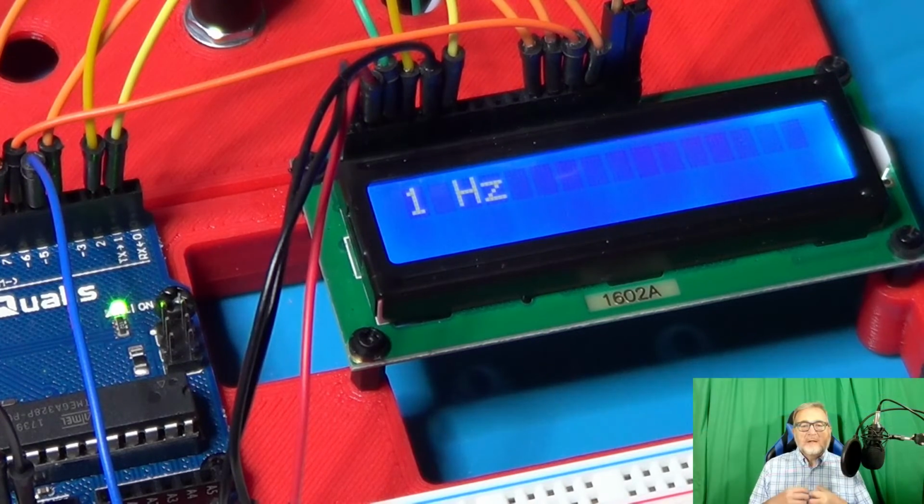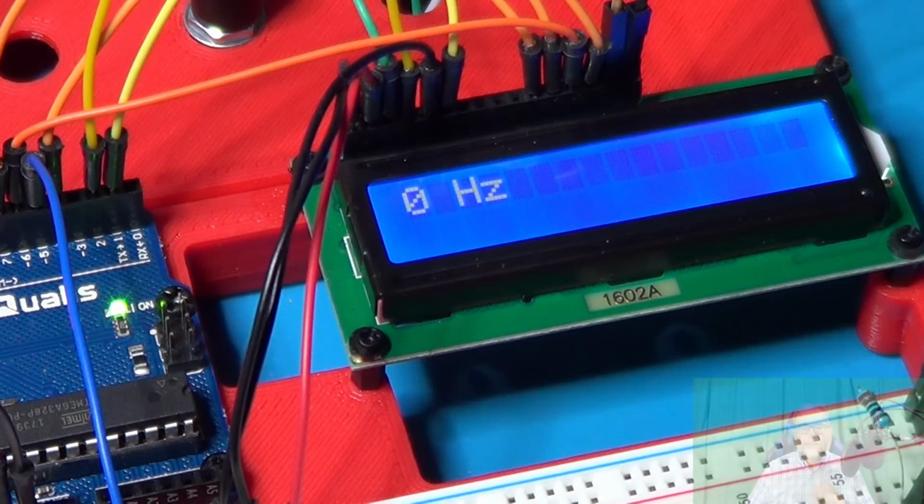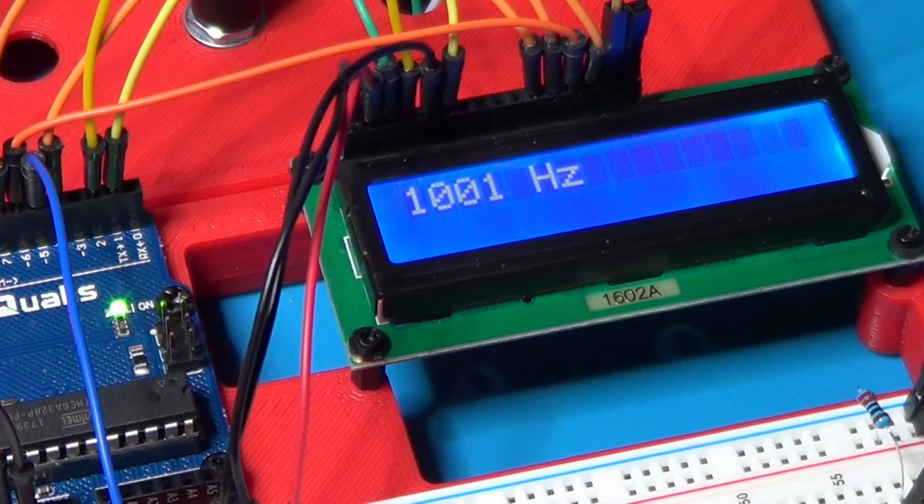So it looks like this frequency counter is perfectly capable of going down to 1 Hz, which is the minimum measurable frequency since the measurement is contained in an integer number. Let's now see what the upper boundary is. So let's go back to 1 kHz. And now, if you remember the circuit from the previous video, that was able to measure fine up to 1200 Hz. Let's see if we can go any further than that.